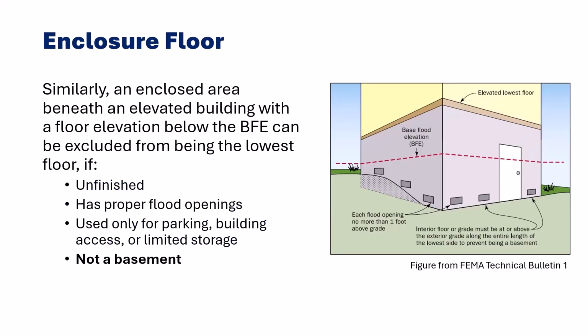The same thing would apply to enclosures below the base flood elevation. They can be excluded from being the lowest floor if they're below BFE, if they're unfinished, have proper flood openings, are used only for parking, building access, or limited storage, and are not in a basement area. That means they're at or above exterior grade on at least one side to prevent them from being a basement.